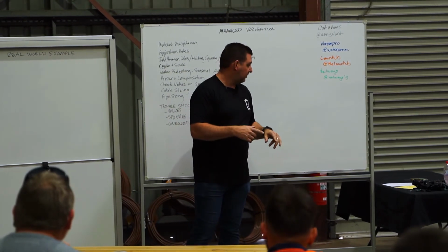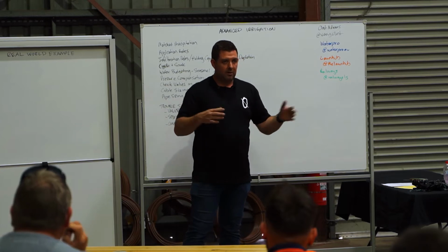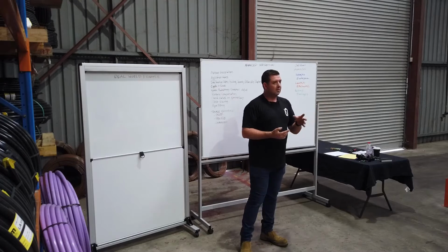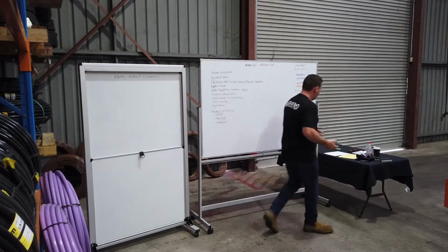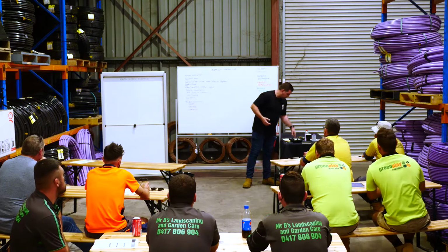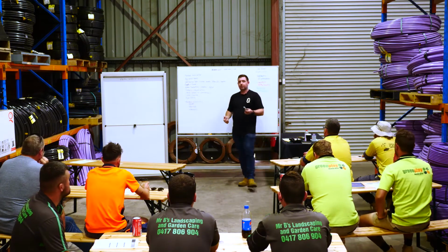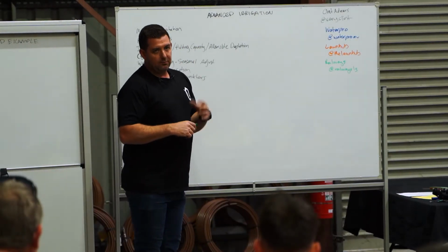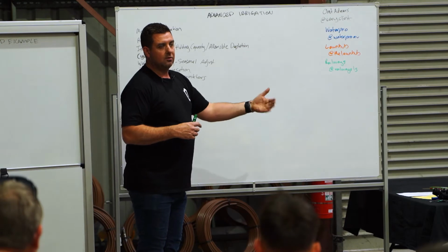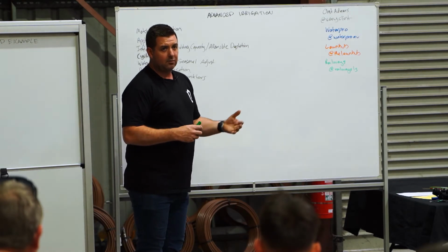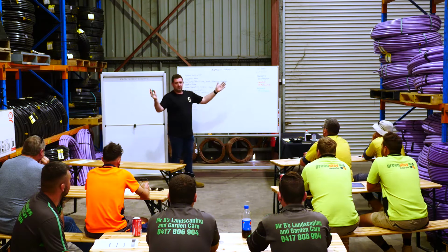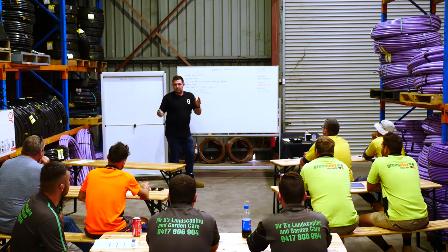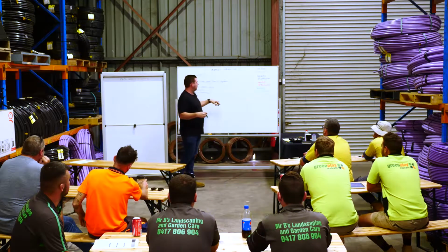Now the precipitation rates of all the different sprinklers vary depending on what you're using. So the Hunter MP rotator, in the 1s, 2s and 3s, you're going to deliver about 11 mil of water per hour per square meter, which is the lowest precipitation rate you'll get from a sprinkler. Then you move up to the R-Van, which is around 14 mil. And then if you jump right out to some of the gear drives and the traditional sprays, the pop-up sprinklers that just spray a full jet fan of water, they're in the 20s to 40 mil an hour. So we're starting to get some really high flow and precipitation.